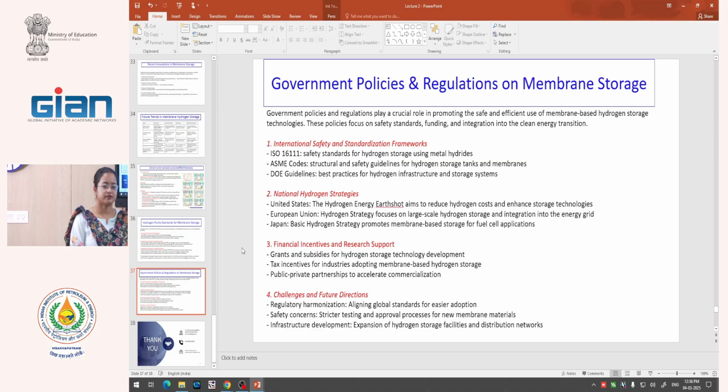Thank you. What's the fabrication method generally used for these hydrogen membranes, to enhance durability? Yes. For polymeric membranes, as I mentioned once, when we use the solvent non-solvent method, it creates pore volumes of a larger size, which we want to avoid in this kind of hydrogen separation application. So in that case, we need a very thin or very dense material.